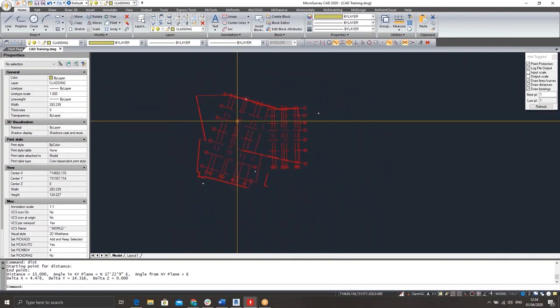So we manipulated, we froze layers that we had of interest. Then what we did is we could thaw the layers, but delete the remaining information first that we're not interested in. So what I will say is that you always want to have your information saved in 2 or 3 different places. So I'm not going to start manipulating the drawing and altering that CAD file unless I know that I have the source information in an email or somewhere else saved.